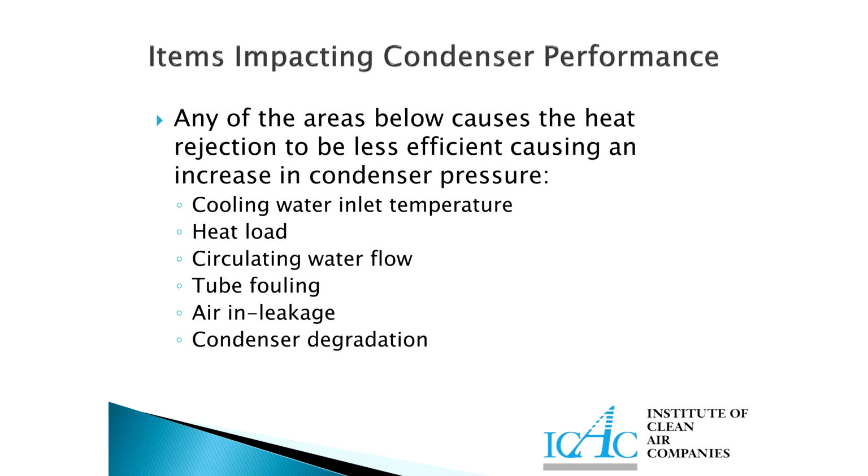On a hot day, usually they have cooling water. Some of the condensers get the cooling water from a lake or from a water stream. Others use cooling towers. If it's a hot day, you've got hot water coming in. Therefore, the condenser is not as efficient as it should be.